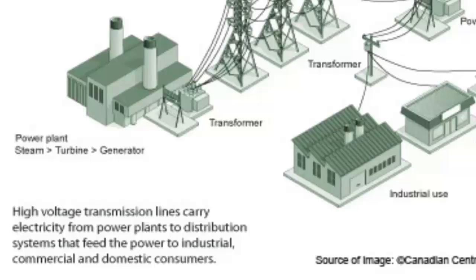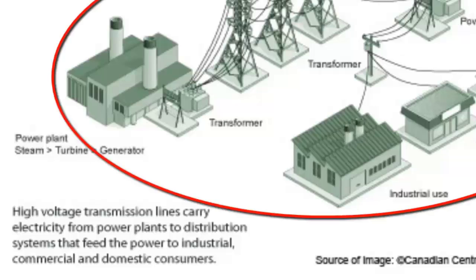DS transformer protection is local and provided by fuses or circuit switchers. Distribution feeders are supplied through reclosers or fuses. Generation connected to the distribution system is typically less than 50 megawatts in capacity, and the electricity produced is locally consumed.